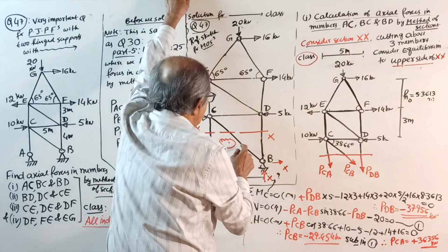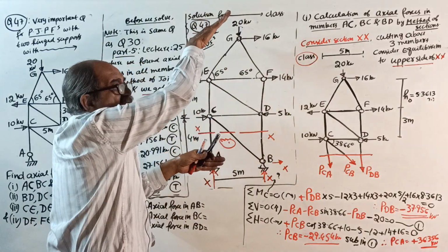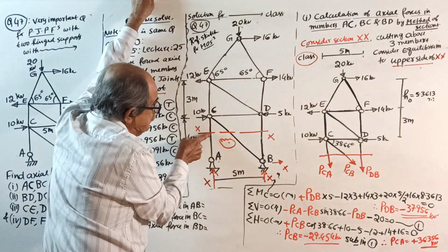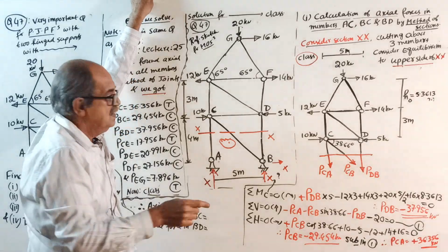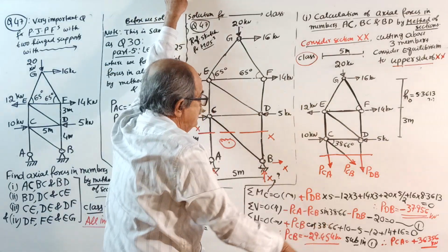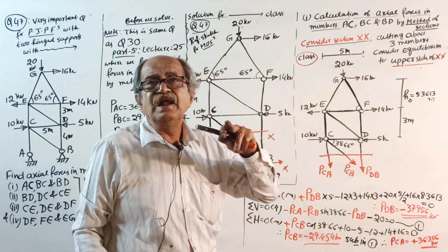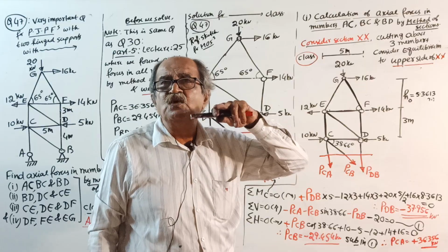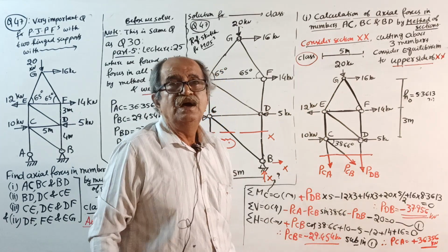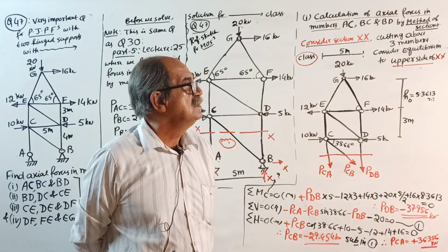Now, see. You are cutting here. That side you sketch the frame. This side where you are not looking, you continue that line. This side should stop now. Where you stopped here, continue and mark all outgoing. If you mark outgoing, later when you consider that force as an axial force, see, right now it is not an axial force. Right now it is an external force.